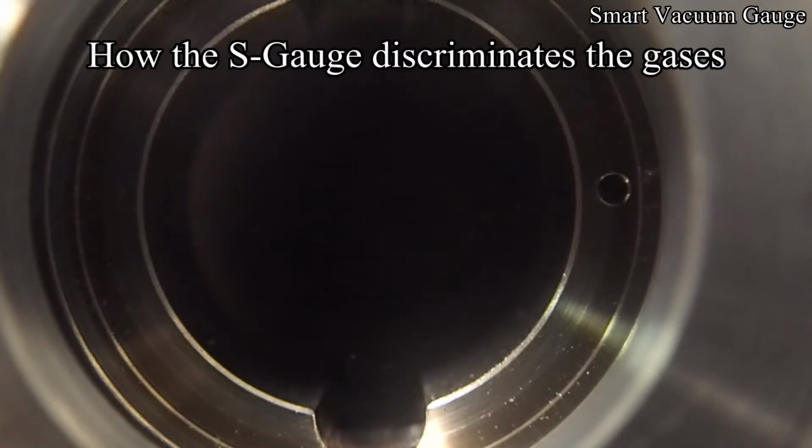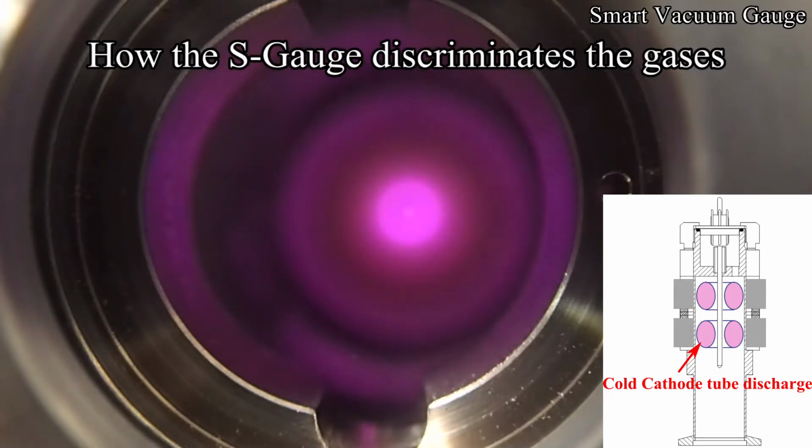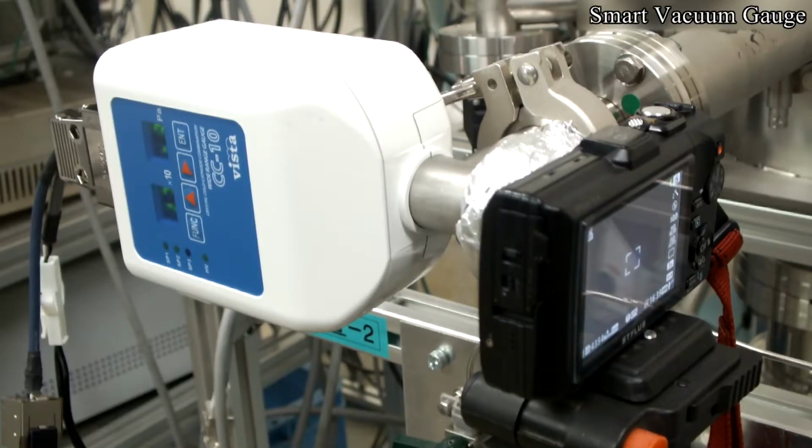How does the S-Gauge determine the gas components? The S-Gauge distinguishes and measures the gas components from the difference in the electrical discharge color of the cold cathode gauge, which is incorporated internally and used as part of the full-range vacuum gauge. The color of the electrical discharge differs according to gas type. Let's operate the S-Gauge and look at the actual electrical discharge inside.